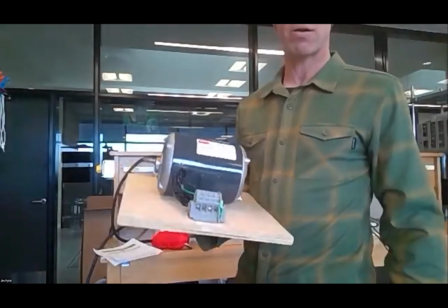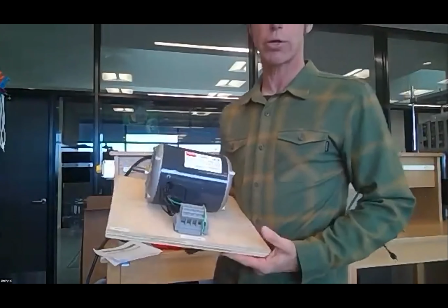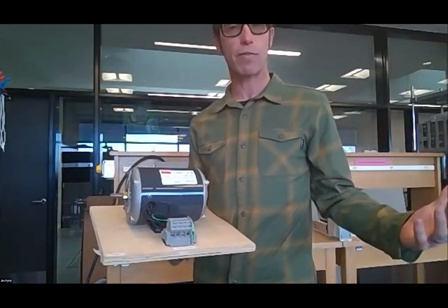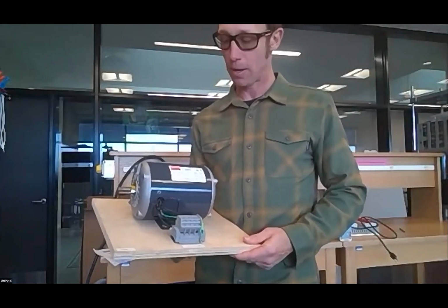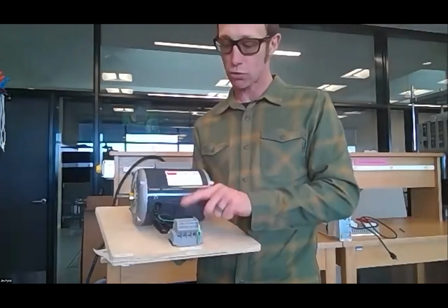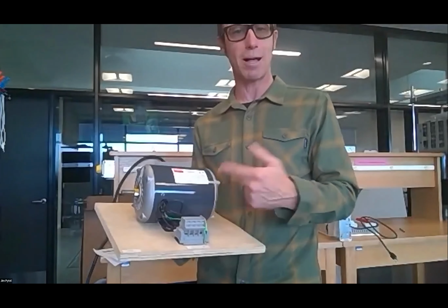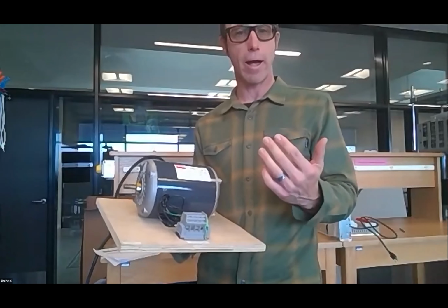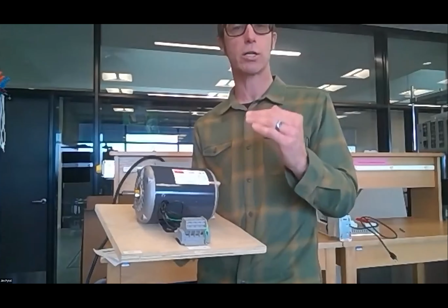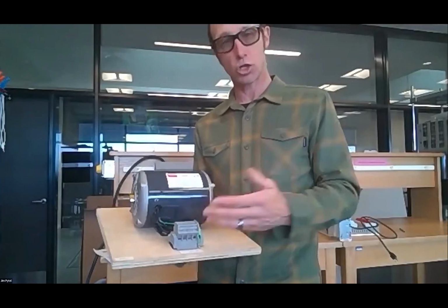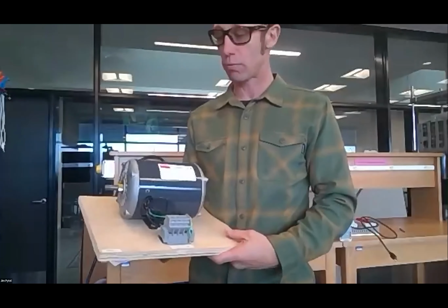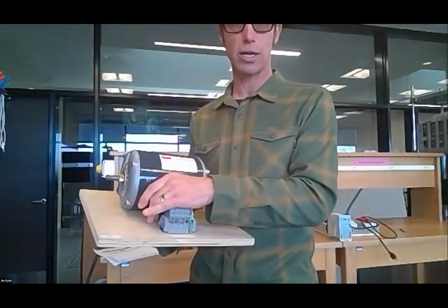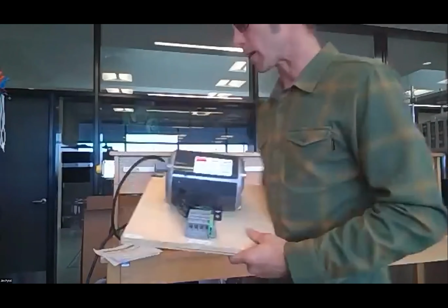This is the really inexpensive quarter horsepower motor we've been using. One of the things I've found is that students are very similar to soldiers: give them a rubber hammer and an anvil, and if you come back in 5 minutes, they'll have broken both of them. So what we've done is taken the terminals from the motor to a terminal block. They can wire it up in Y configuration, high voltage or low voltage, and check the insulation and winding resistance, keeping them out of actually touching the wires by using the terminal blocks.